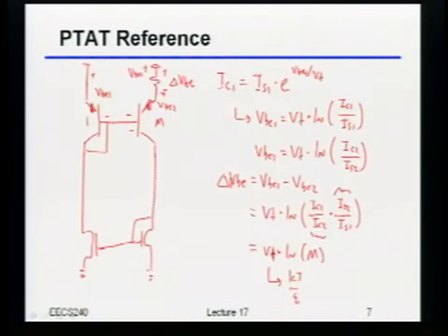Yeah, this thermal voltage is proportional to temperature, and how did the thermal voltage come into the picture? What type of element did we have to use? Yeah, we had to use a BJT or a diode, right? Because with a BJT or a diode, the amount of current is exponential and related to that thermal voltage, okay? So again, this is really just a reminder for any of those references: keep in mind what's the fundamental physical thing that's popping out of there that's allowing you to actually build this, okay?